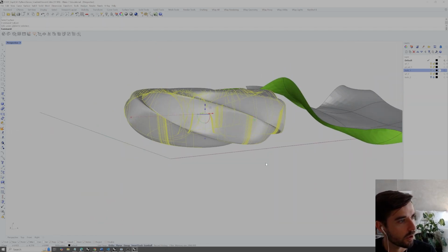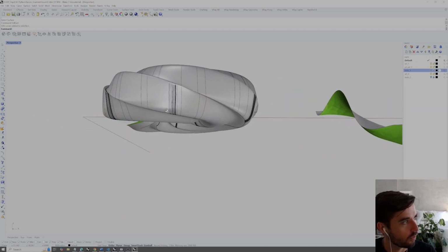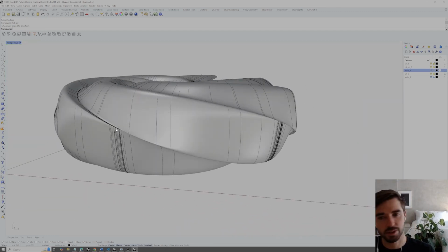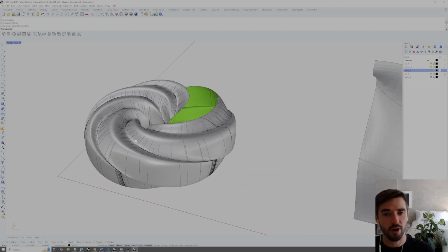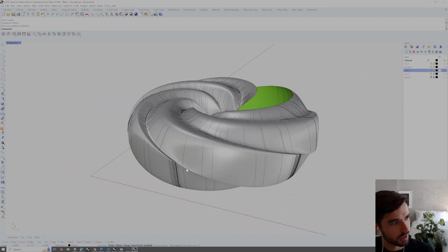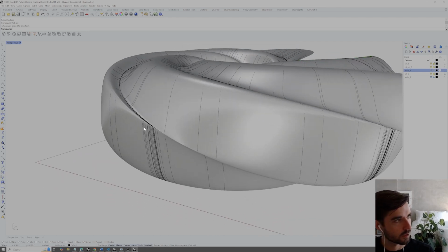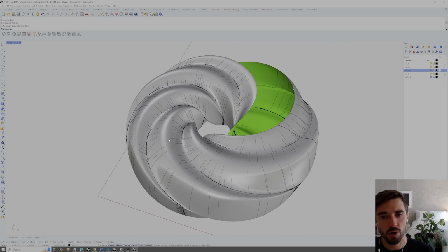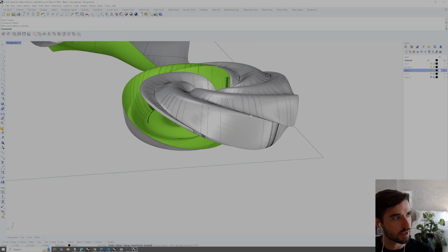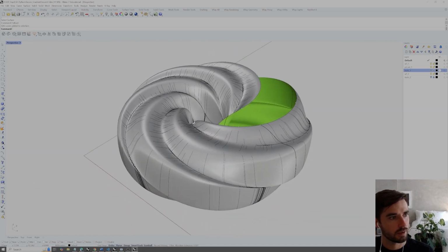And we can see where flow starts to happen over these edges. So it's even giving us a kind of understanding there of where a kind of gutter system is needed, or maybe a reveal that might need to be placed in this surface in order for rain to just not drip down the surface. We could also develop a texture that is actually simulating the wear on the surface or the weathering on the surface based on this rain flow.